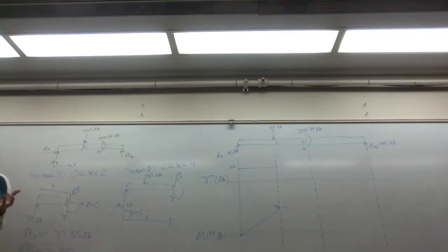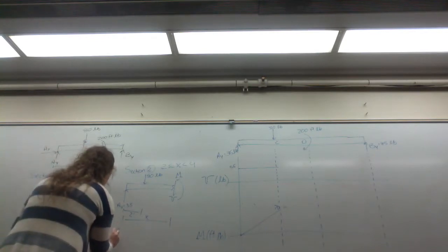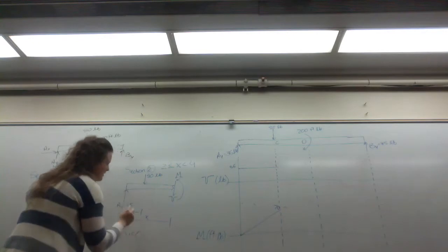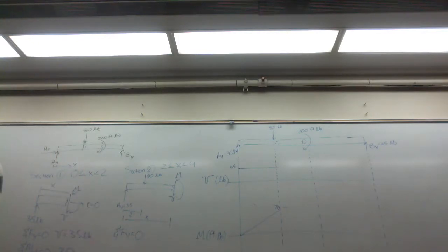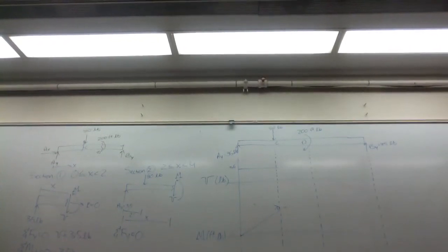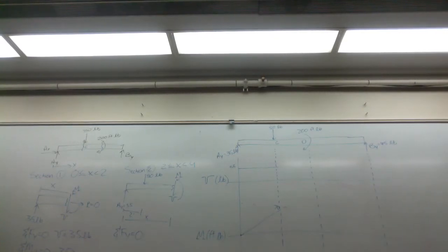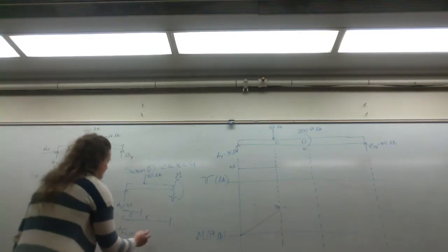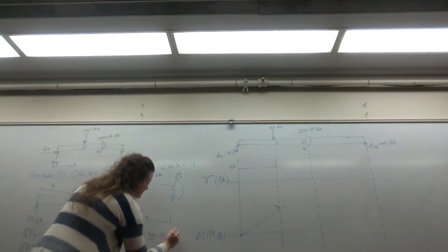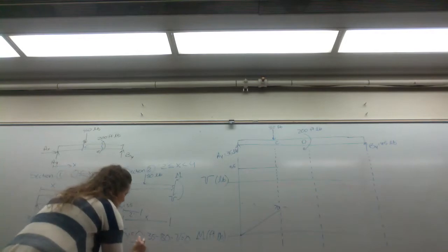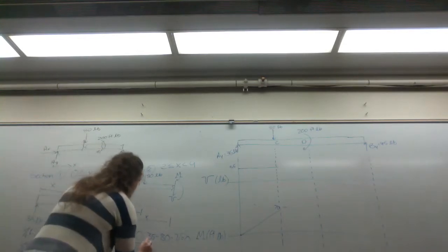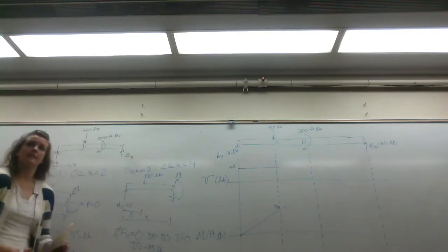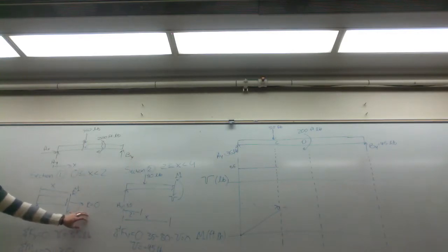You guys should have it down. So your shear force is what? What's your shear force, Chenley? You don't know? Can anyone help Chenley out? Yes, Sarah? 35, minus 80, minus your shear, is 0. And solving for the shear, you get negative 45 pounds. That makes sense, Shenlang? It's just your equation of equilibrium, sum of the forces in the y.